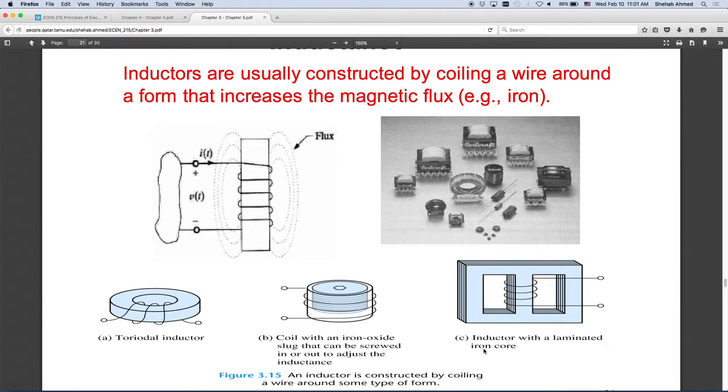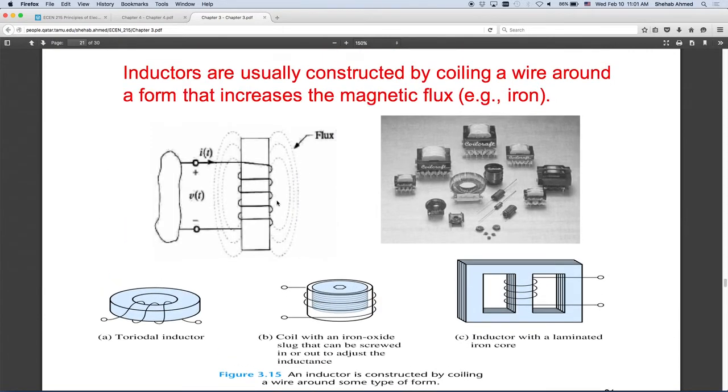Ideally speaking, of course. Practically, these inductors are basically made of electrical wires, and you can wind them around a core or not. It does not really matter. If you don't put a core in the middle, then you don't have a defined place for the flux to flow, right? Then flux can go in many different directions. You would like the flux to flow in a certain defined path so that it can link all the turns of wire that you're pushing current through.